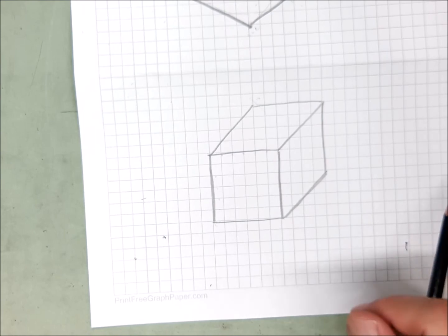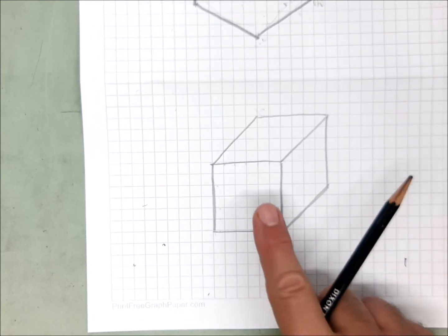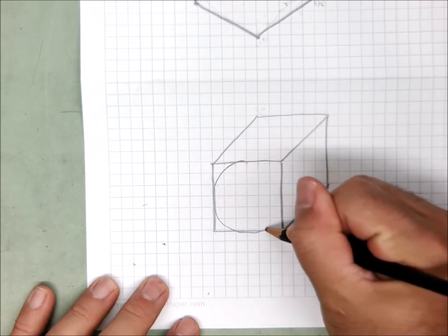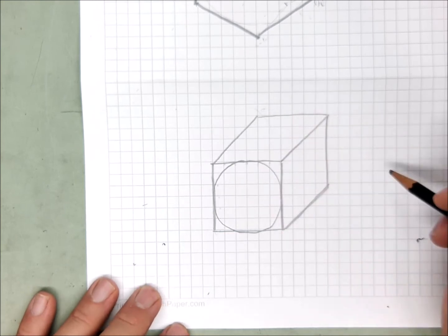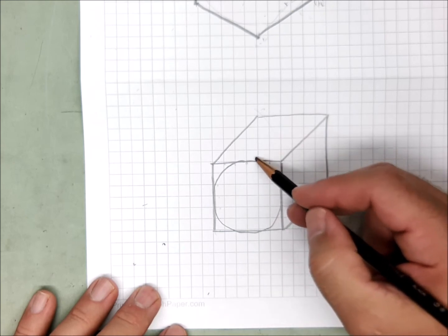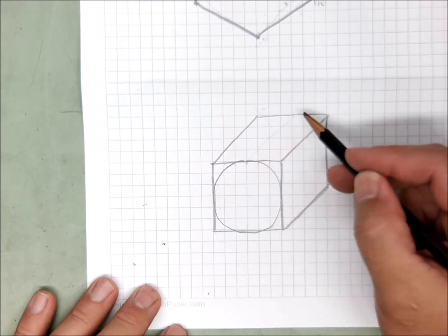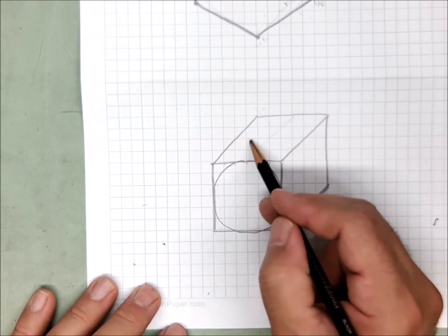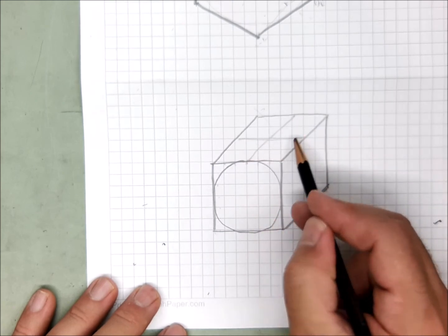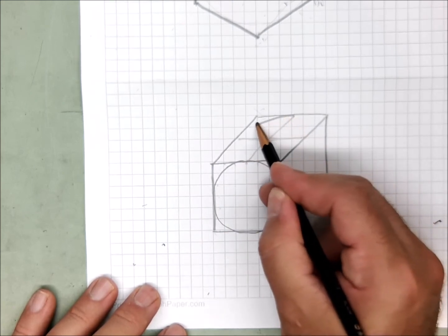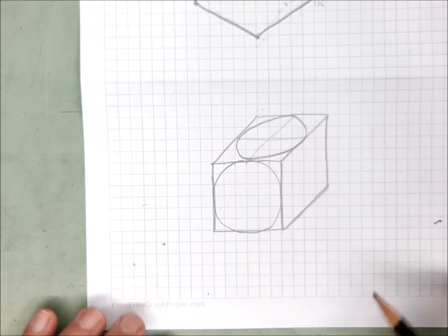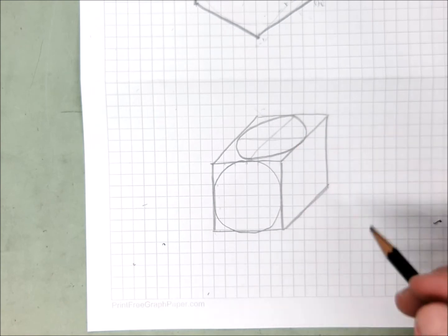So, if you were drawing circles in oblique, if they are on the front face, well, then they are going to be round. But if you're drawing them in the top face, well, now all of a sudden, weirdness happens. Right? So you can think about it like, well, where would the center be? The center would be there. If I had to make a center mark, center mark would be there. So my circle would be kind of squished. Kind of a twisted and squished and weird looking ellipse up on that top surface.